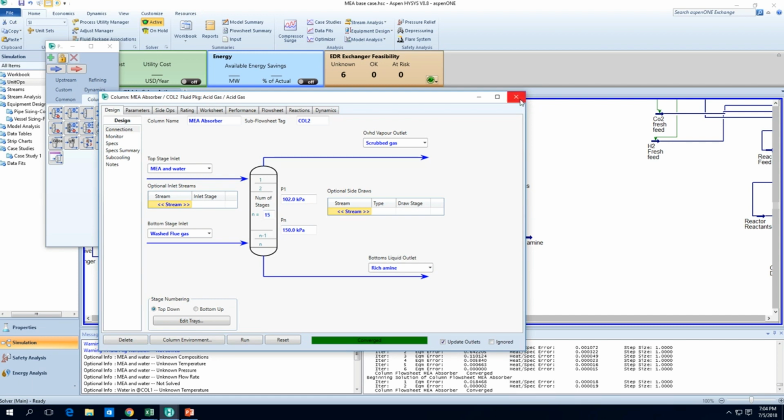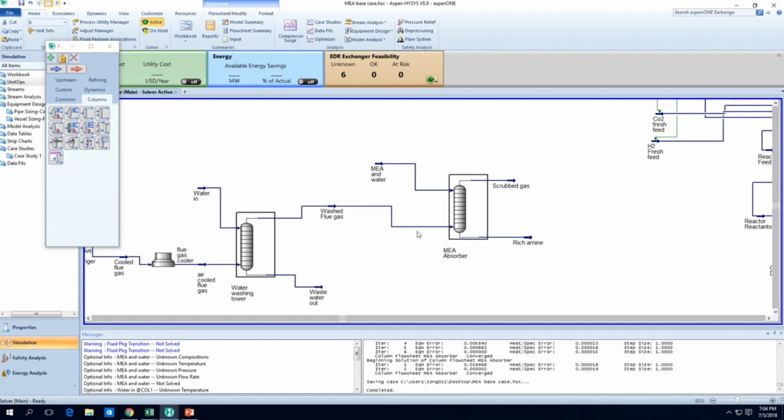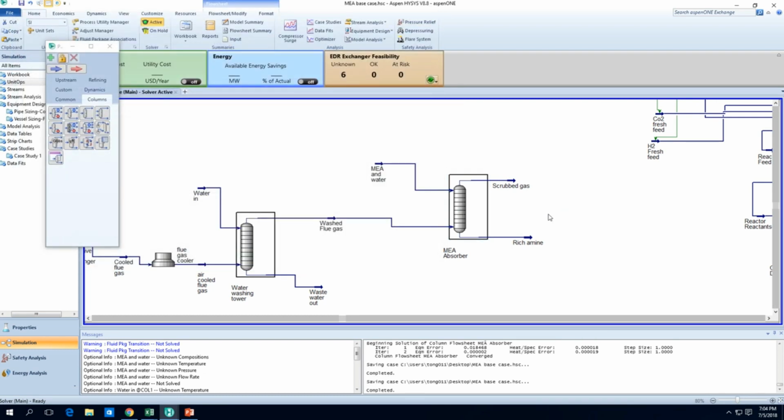to absorb the amines better. And usually we don't exceed 15 stages for, let's say, a packed tower, because otherwise it can get too high. I mean, that's just a general rule of thumb. It doesn't have to always be followed, but there are always cost considerations. So I like to keep it at less than 15 or 20. Okay, so let's try the series configuration.